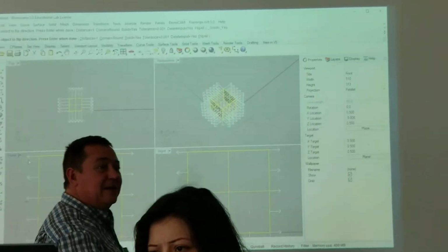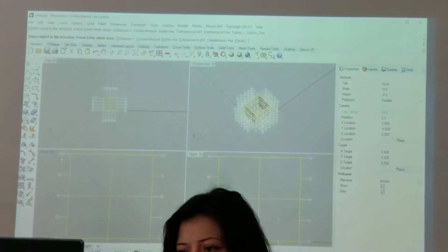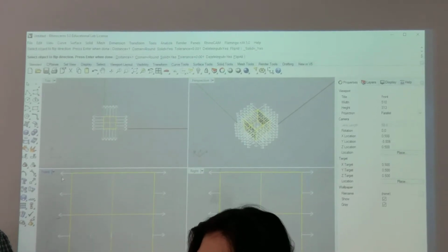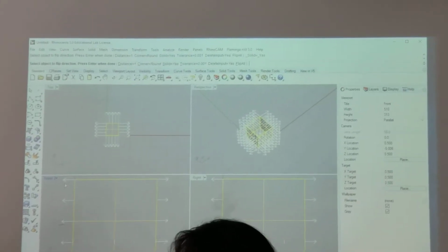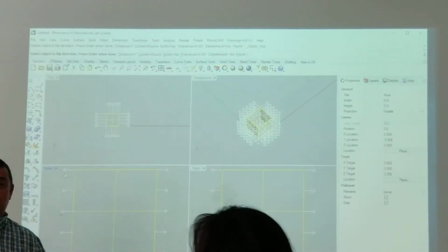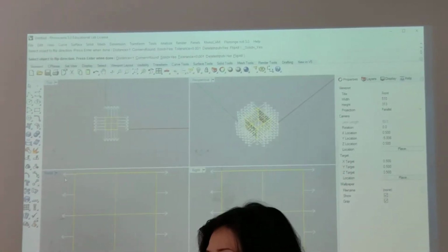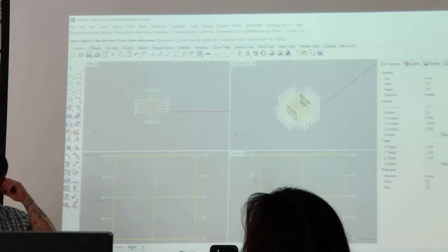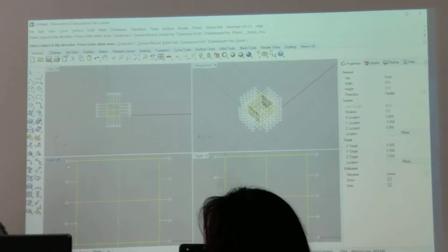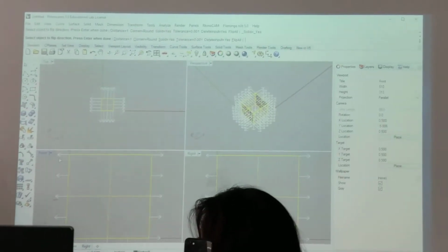Here's the directionality of the surface. Those are called the surface normals. They can be abnormal. It is possible to take a closed cube and turn it inside out. The 3D printer will not like you for that. It is possible to build objects where some of the surfaces' directionality faces the outside and some of the surfaces that are supposed to face the outside face the inside. And the 3D printer will not like that.